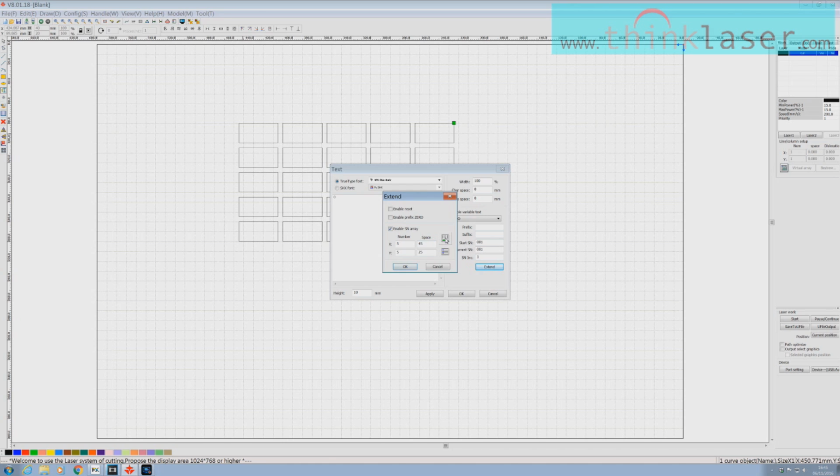And now we've got these two strange little icons here, and we have a choice of 2 when we flip on this one. This one looks as though it reads left to right. In other words, the serial number runs across the page like that. And then we've got this other little icon here, which tells us we're either going to have the serial numbers running backwards and forwards, 1, 2, 3, 4, 5, 6, 7, 8, 9, 10, 11, 12, 13, etc., like a snake, or we want them all in one direction, which is what I've chosen to use. So we should get what we want. OK. Apply. OK.